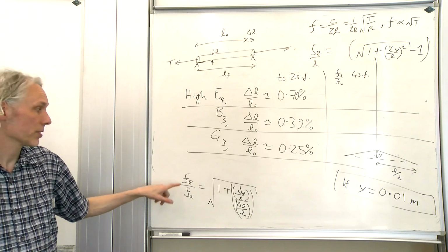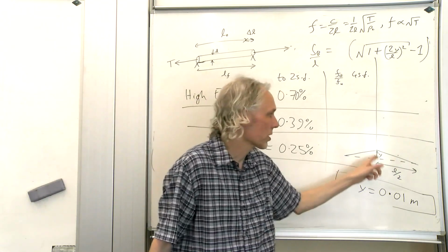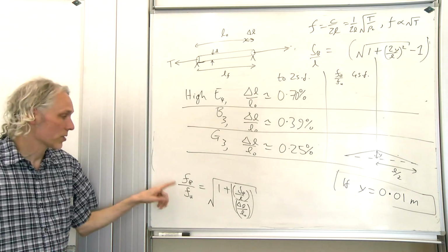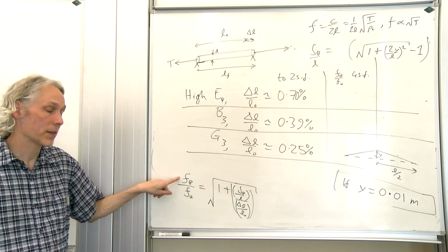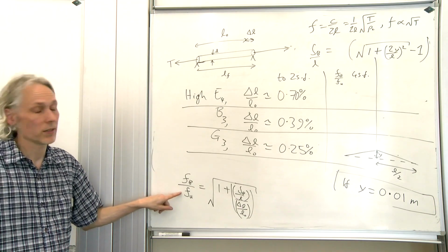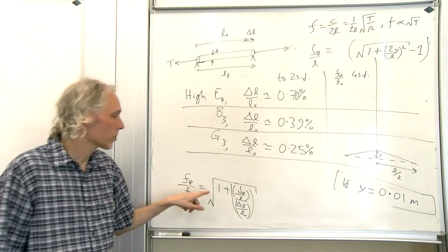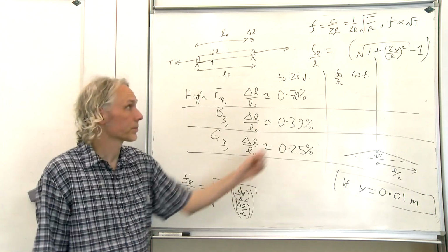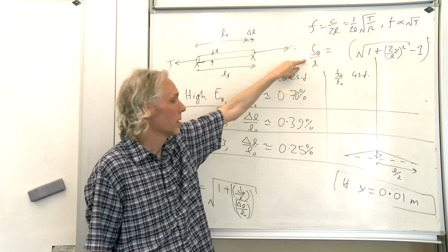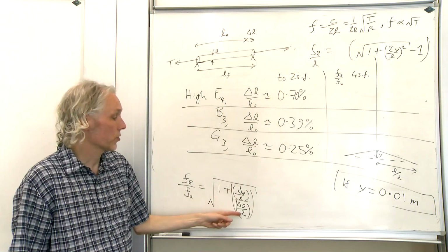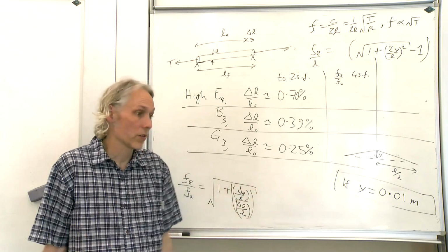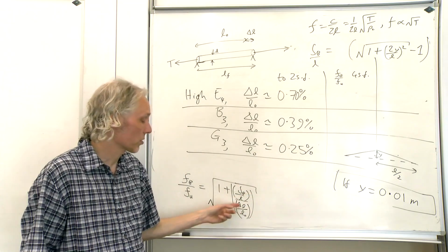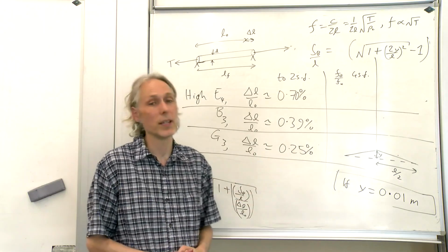We've got this formula which tells us the frequency of this section of string between here and here is changed in its frequency, for frequency bent being a ratio with the frequency of the unbent string, given by square root of 1 plus the strain due to bending, given by this formula here, divided by the strain through which the string was stretched, this ratio of stretch to get it up to tension in the first place.